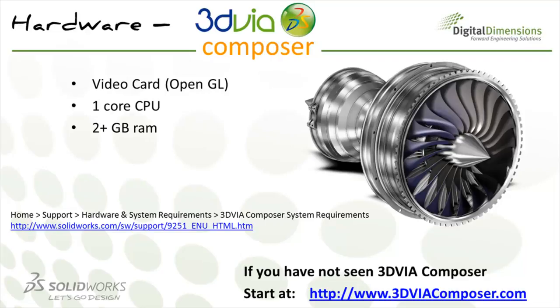On that side, it's still probably a good idea to talk about some basic hardware requirements. It does work a little bit better with an OpenGL video card. Again, not required. Keep in mind you might be running Composer on a machine that's not even running SOLIDWORKS, so this might not even be the CAD guy. Again, multiple cores is always a good idea.